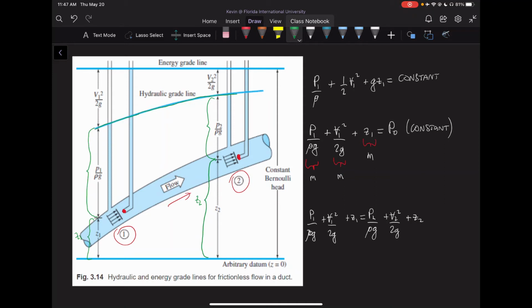So we can see that there's a difference if we just take the term of static pressure and height, we actually have a difference between the two systems. Now, if we add all three terms together, we actually get a line that is flat at the top. That makes sense. We have a constant Bernoulli equation. Our Bernoulli equation is equal to a constant. So it means that if we add all three terms together, we should have a flat line, a line that shows us exactly how much the three terms are adding to. So our velocity term is dictated by this.